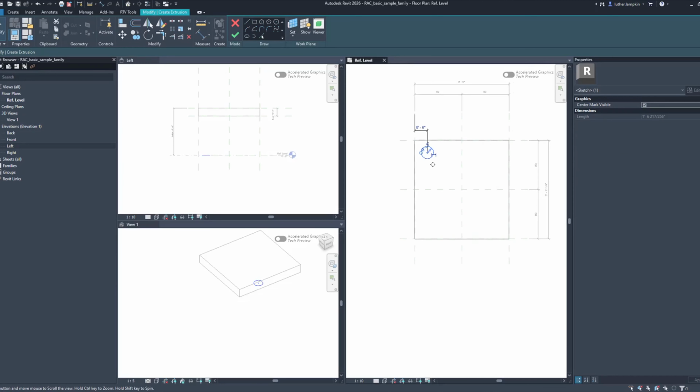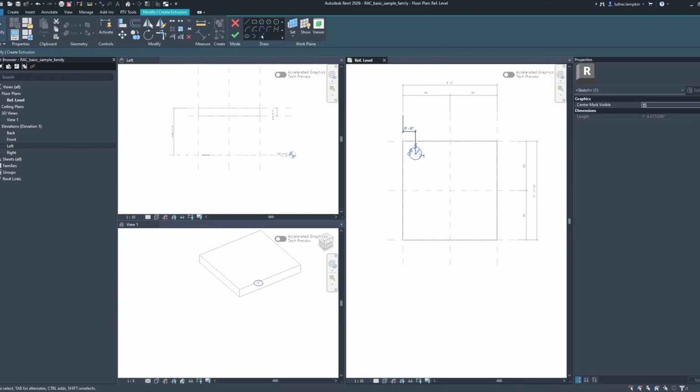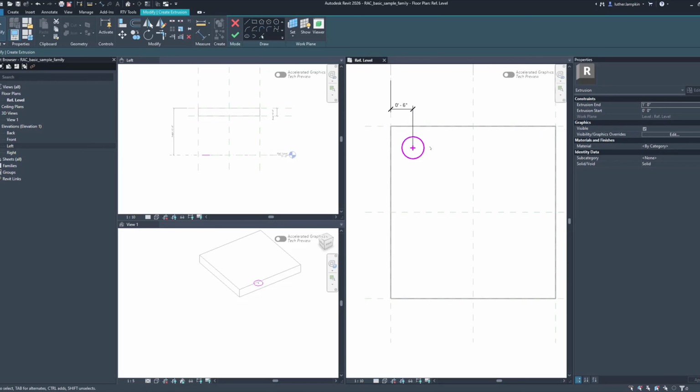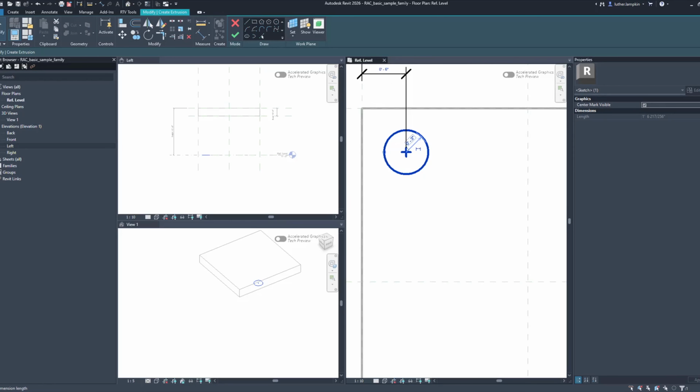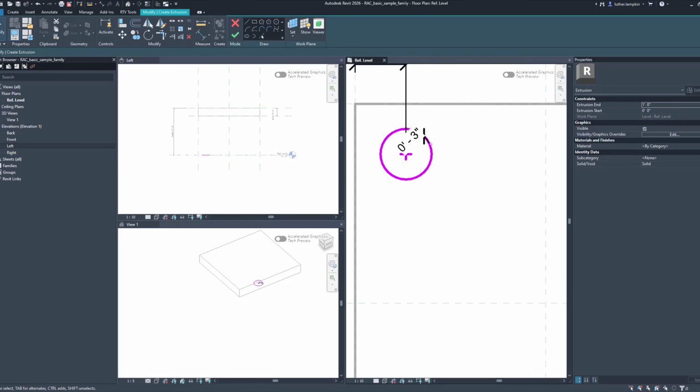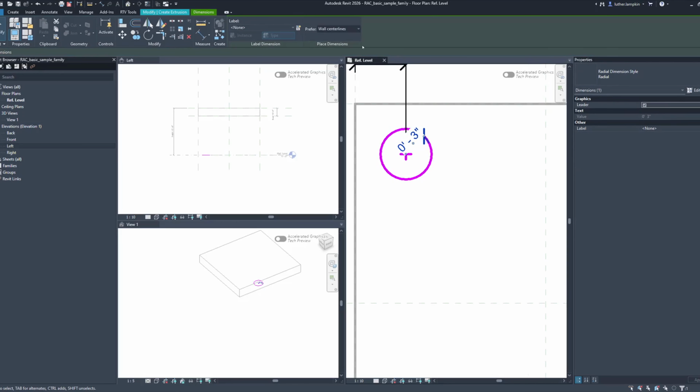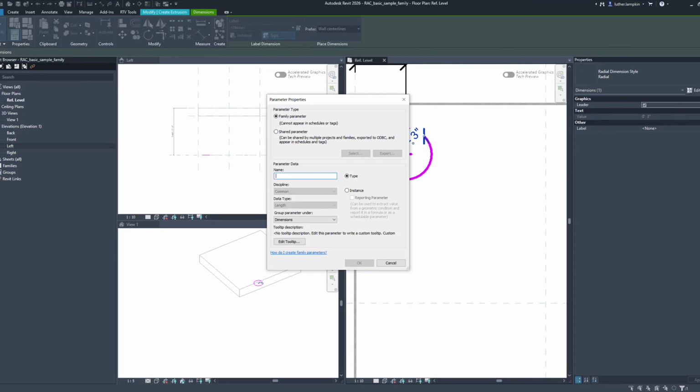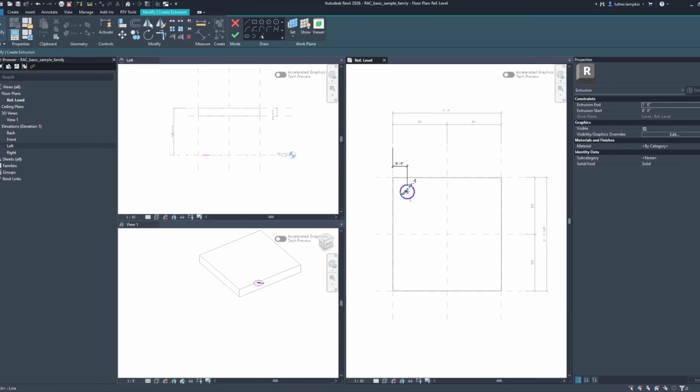Cool. Now I can click on this. I can pick a radius as well, but we'll do that in a second. If I click on this circle, you'll see I got this dimension. Click on that to make that a dimension. Now I may want a radius for this, so I click here to create a label. Well, we're cooking now. Just say radius, and now I'll just hit OK. So now I got that. Now I'm controlling everything.